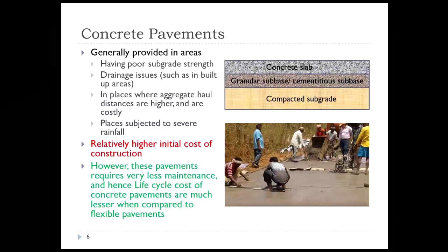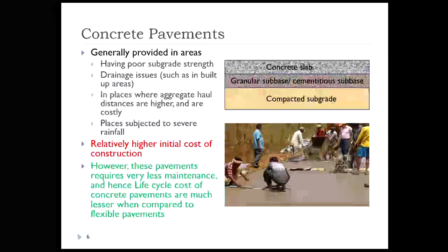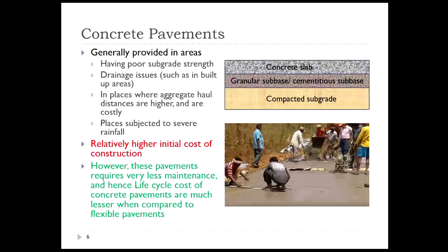Now, what we need to realize is that when you look at the life cycle costs of these two pavements, a flexible pavement will receive a surfacing at the end of the 5th year. It may require a rehabilitation at the end of, say, the 10th year.